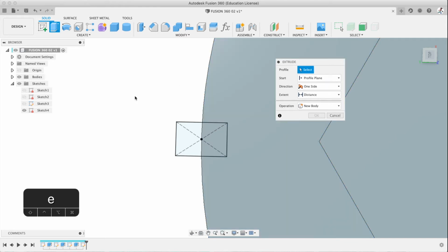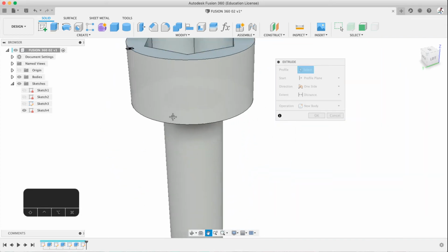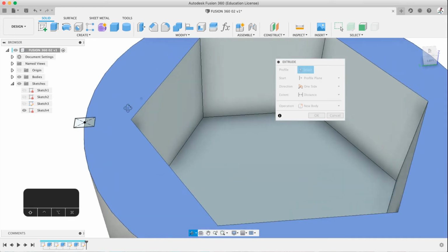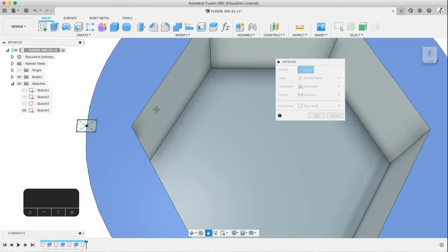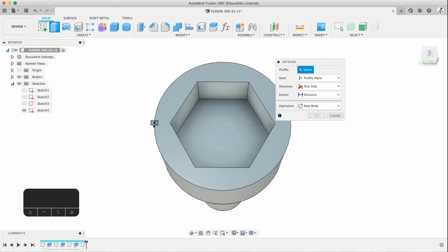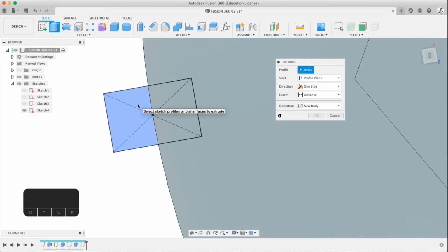And now I can actually extrude just this section where the circle itself is cutting out. This section, I can also extrude this. Anything on this plane, right? Let me move this. The plane of this sketch can be extruded. And every single shape and edge is a separate edge, as long as it's a solid edge. If it has a hole in it somewhere, not a complete edge, it won't give you that option. So here we go. I have this one and this one.